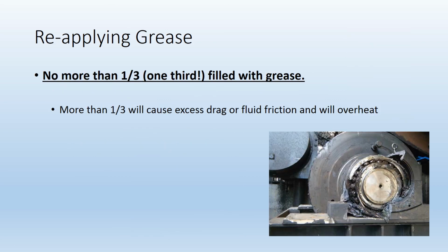When applying grease to a bearing, how much grease do you put in? Up to 1/3. Never put more than 1/3 of grease into a bearing. If more than 1/3 is put in, that's going to cause excessive internal fluid drag and cause overheating.